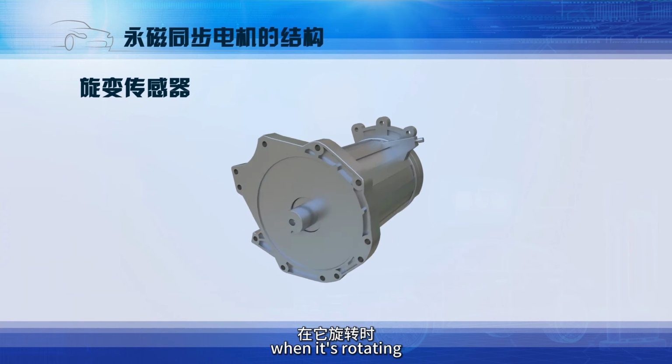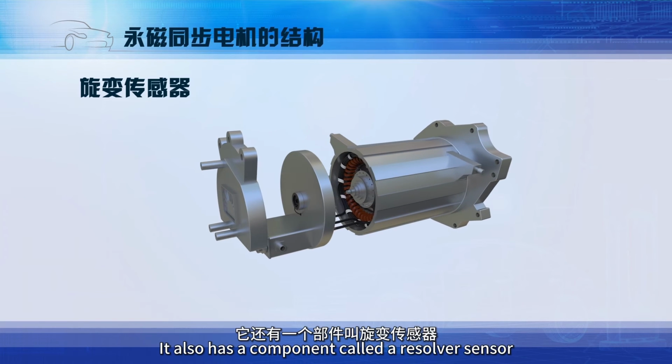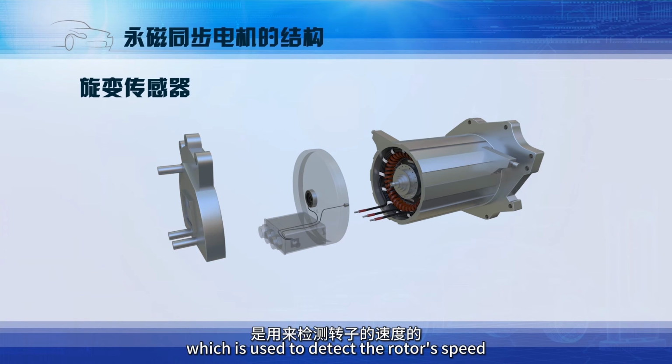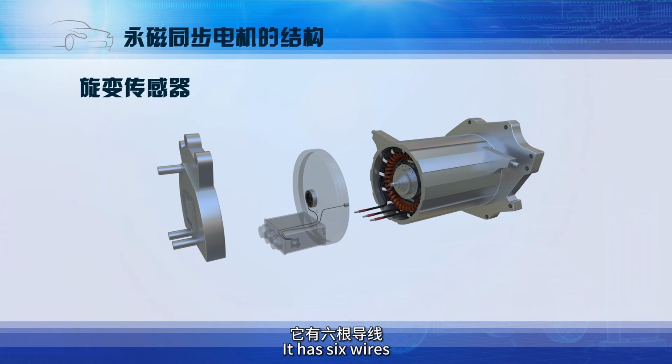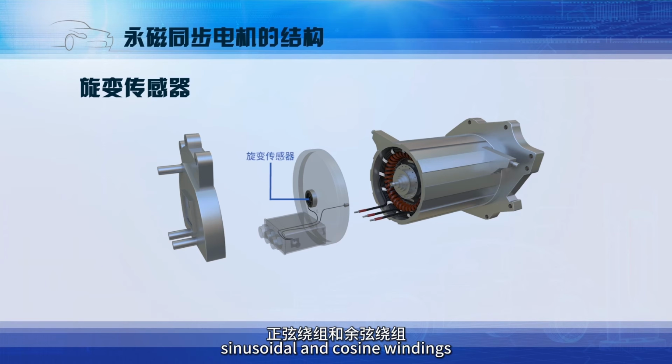As we know, an engine needs a crankshaft position sensor to detect the crankshaft's angle and rotate speed when it's rotating. What about the permanent magnet synchronous motor? It also has a component called a resolver sensor, which is used to detect the rotor's speed. It has 6 wires and 3 windings: the excitation winding, sinusoidal winding, and cosine winding. The control unit energizes the excitation winding, and when the rotor rotates, sinusoidal and cosine windings output 2 waveforms to detect the rotor's speed and position.